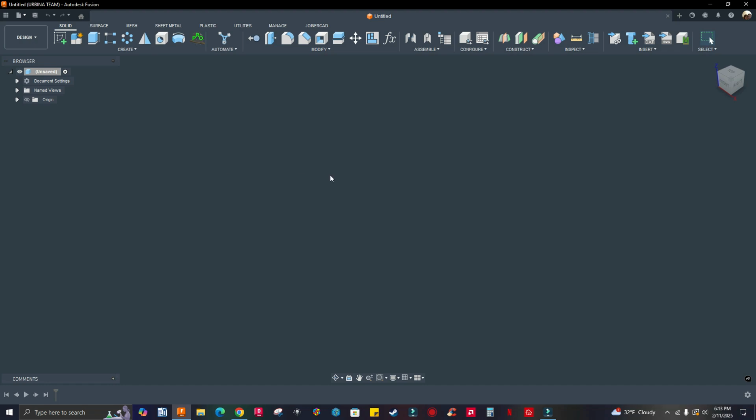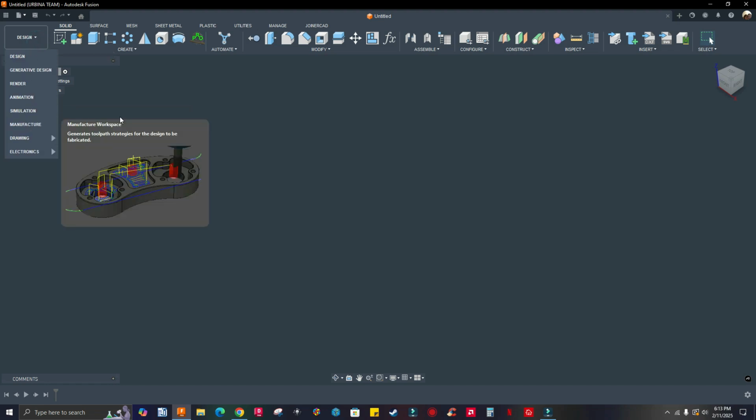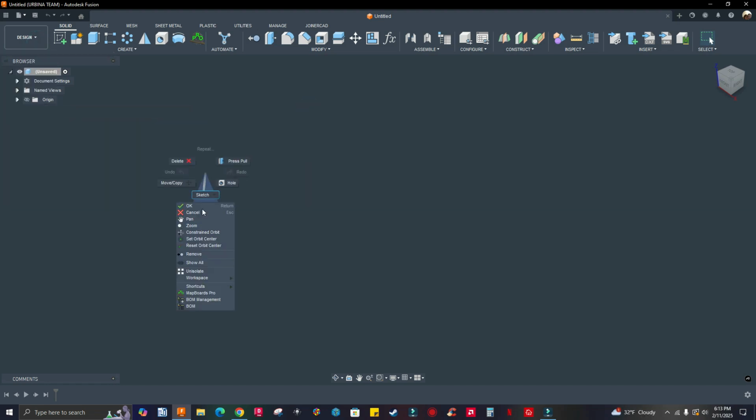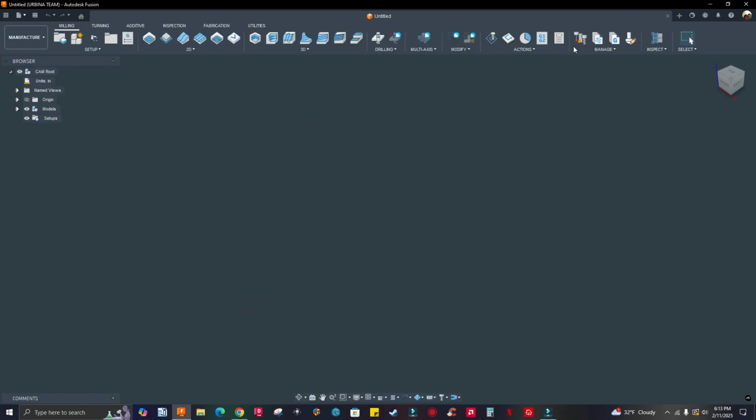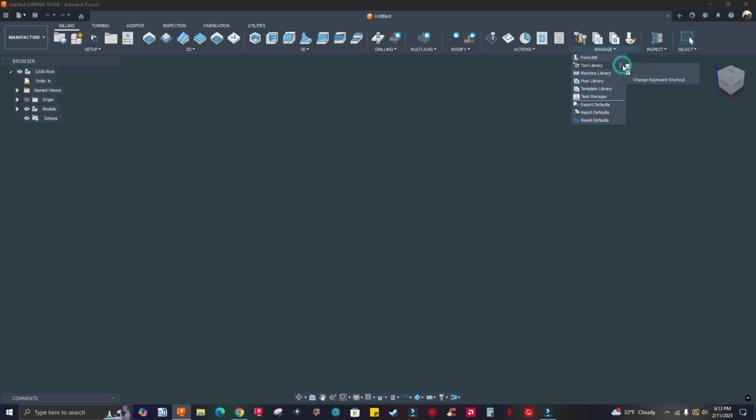All right. So the first thing you're gonna have to do is go to Manufacture Workspace, and there's two ways to get there. So the first one is just click on the sign, go down to Manufacture. And the second way is just right click, go down to workspace, manufacture, okay? And then go to tool library. If you don't have this, just click on manage, select tool library. You can add it to the toolbar by clicking on these three dots right here.